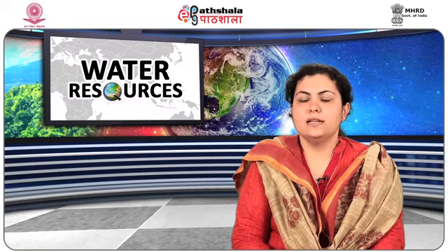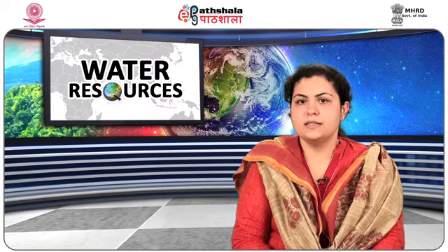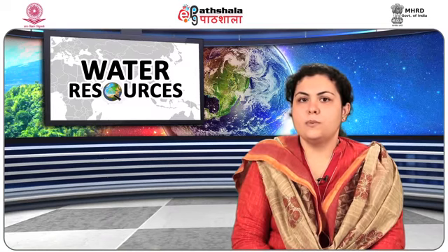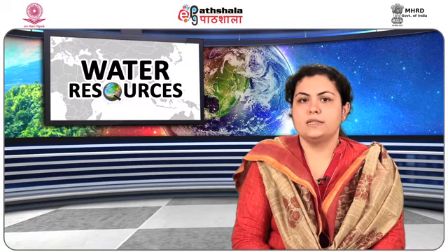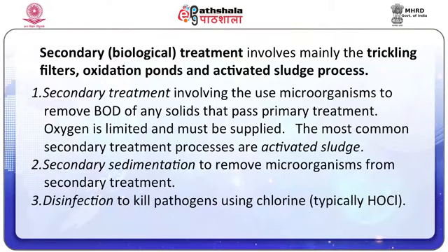Secondary treatment technologies include the basic activated sludge process, the variants of pond and constructed wetland systems, trickling filters and other forms of treatment which use biological activity to break down organic matter. It involves mainly trickling filters, oxidation ponds and the activated sludge process. First, secondary treatment involves the use of microorganisms to remove BOD of any solids that pass primary treatment. Oxygen is limited and must be supplied. The most common secondary treatment process is activated sludge.